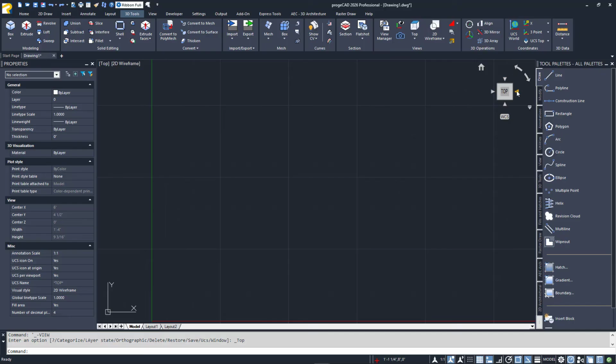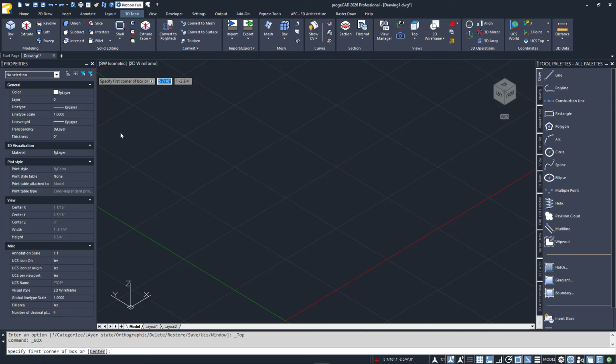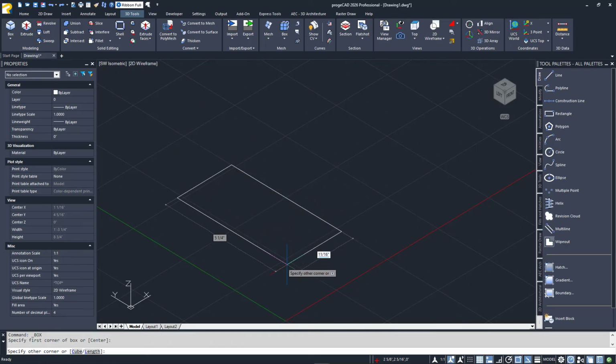When you click on the main tile of each side, you'll go right to that view. Finally, each corner of the cube is a shortcut to view your model in the corresponding isometric projection. I'll click on the Southwest Isometric corner to duplicate what we saw using the Viewport controls. I'm going to stay in this isometric view to show you the next viewing tool, but to see it best, I'll need some kind of 3D object, so I'll quickly add a box and we'll return to learn about it later.